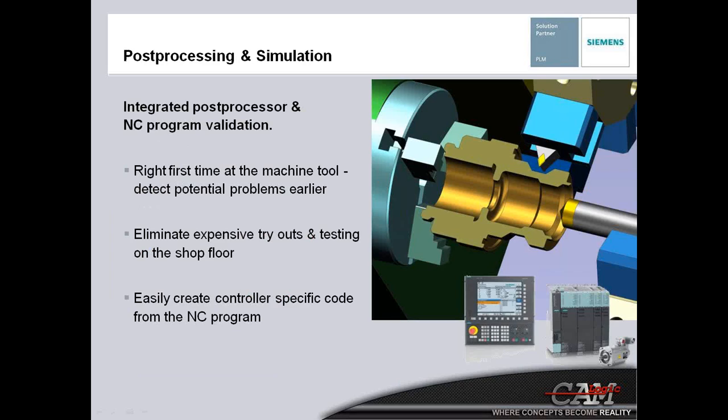By providing good output from the CAM system, you should be able to reduce this time and effort and still avoid machining mistakes. And this is even more important as machines become more advanced, with the 5-axis or multiple machining options with the mill and turn, both within one machine.